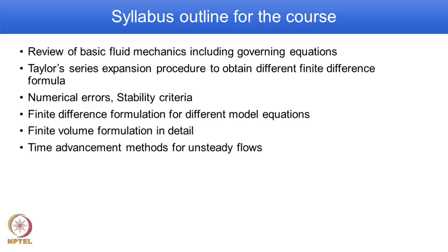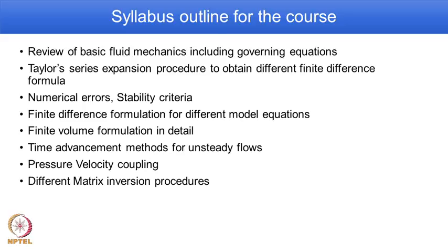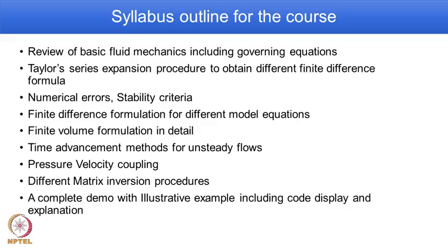How to do unsteady equations, which means time advancement methods for unsteady flows. Then another important procedure, what is known as pressure velocity coupling, which is linking the momentum equations and the continuity equation. All these equations when discretized will result in what is known as linear algebraic equations. Then to solve, you have to know different matrix inversion procedures. We will go over those procedures also.